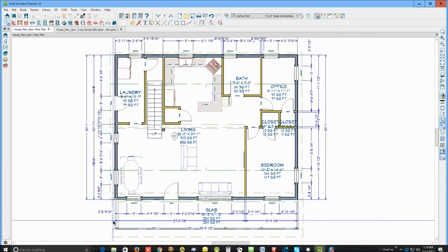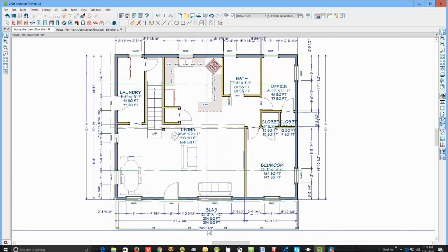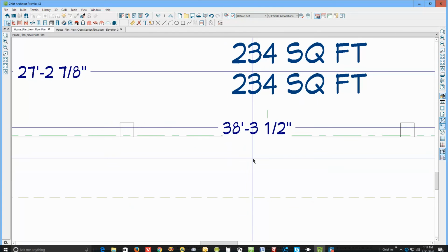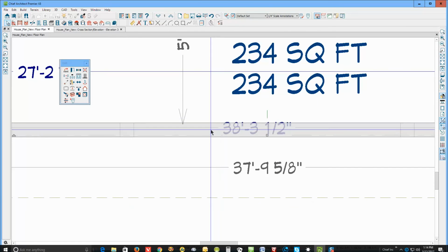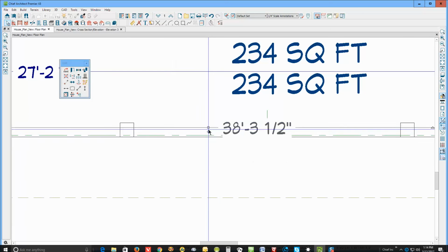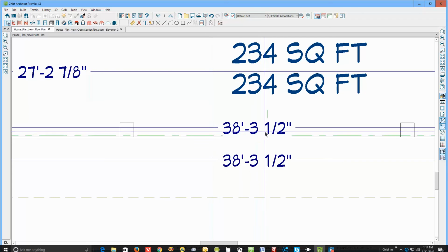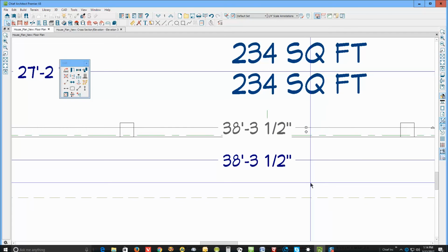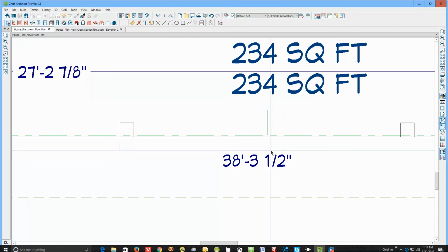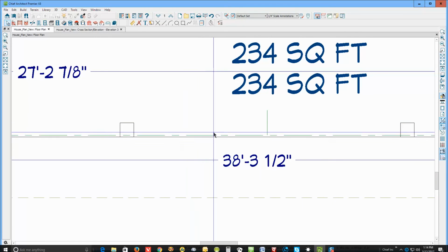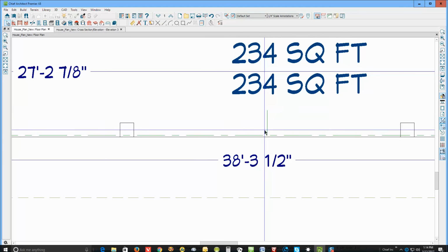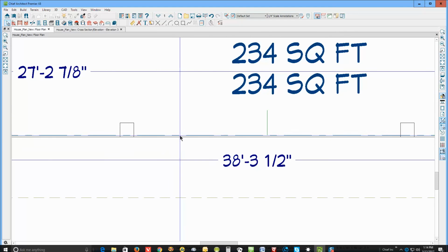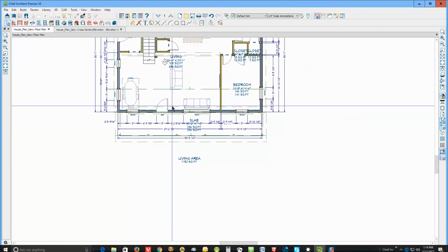Okay, here's the shed roof. You got that properly located. And I can tell because, get this dimension out of the way. Oh, there's another one. I'm going to delete that one. Okay, this little dashed line here with a perpendicular on it is the roof baseline, and it should be on the edge of the structural wall over which it bears, and that's correct.